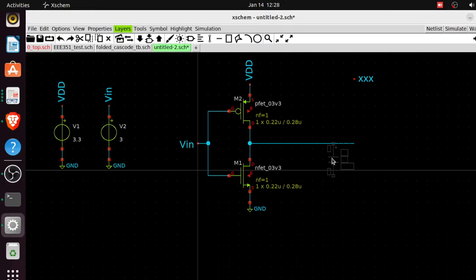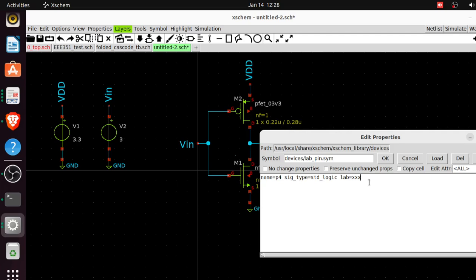So here's our capacitor. So I do the wiring for the ground. It needs to be grounded. So C for copy, remember, but not digital copy. Then I can now move, M for move. Yeah, then I can label this V out.